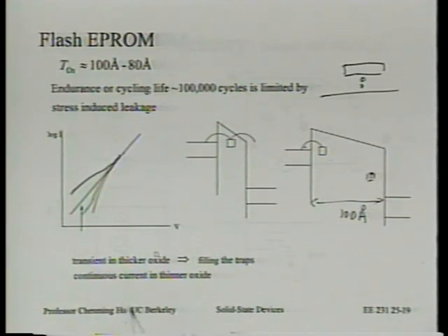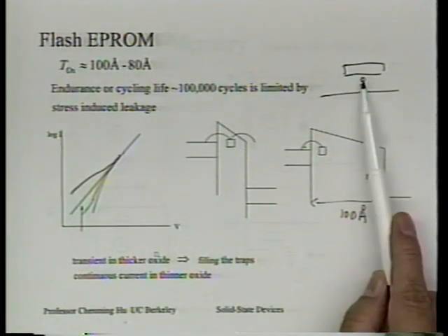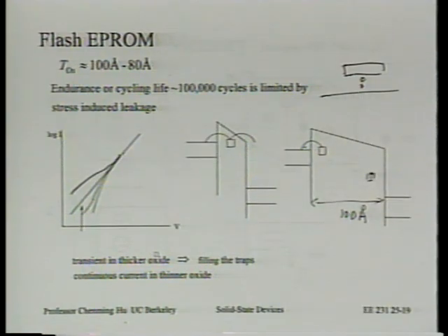When this happens, it usually doesn't happen throughout the array. If you have, say, 64 megabit of transistors, usually a few dozen of them will fail first. So it's totally probabilistic. It's a cell where you just happen to have two of the traps lining up physically. Now those will become the ones that give trouble.